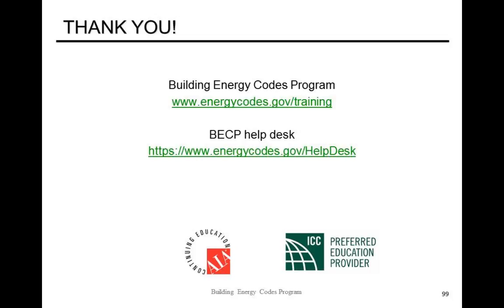projects, unless, however, you're changing the control system. So if you're only changing the fixtures, you have to comply with the LPD and some controls, but not daylighting. If you are going to yank out all your controls and start over, if you're changing the controls, then you would have to upgrade to daylighting if your space has that capability. But in general, no, it's not required.